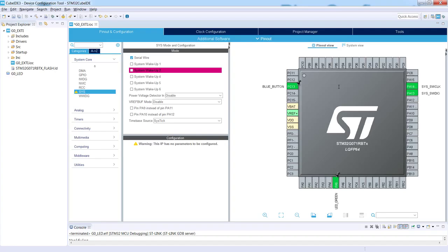You can refer to those settings within the main.h file. All the labels are stored there. Concerning the pins, this is all we would like to do. We do not perform any clock configuration modification. What we need to do as well is to properly configure this external interrupt input pin to be active on falling edge. How to do this?